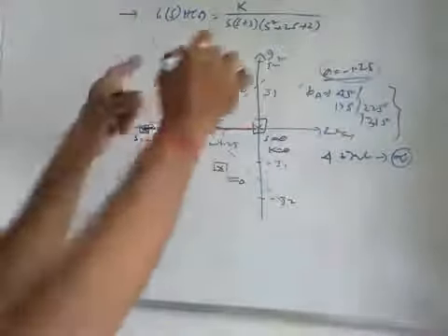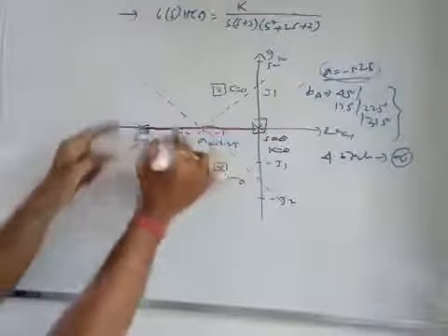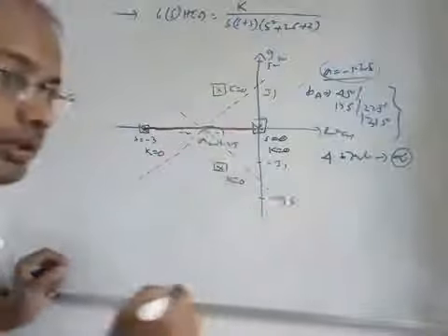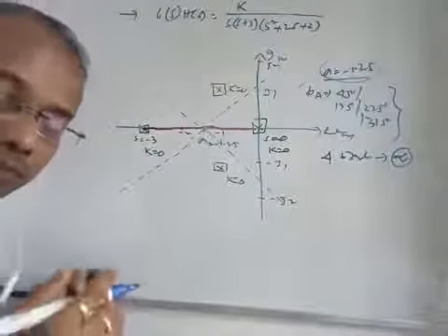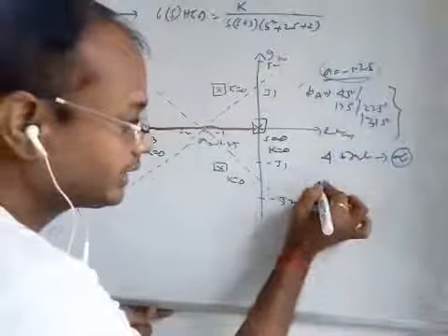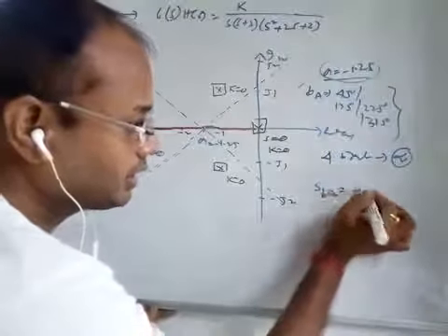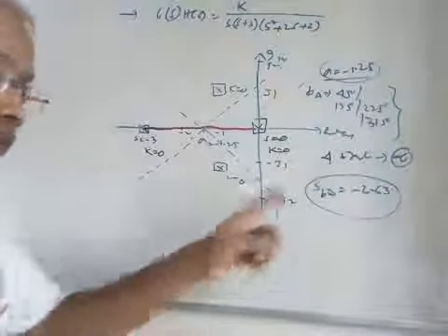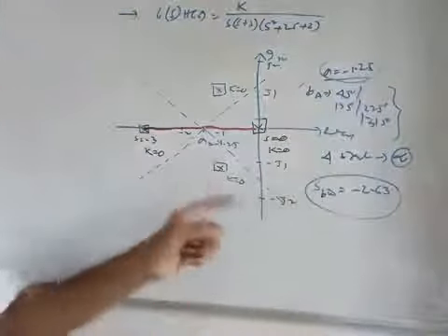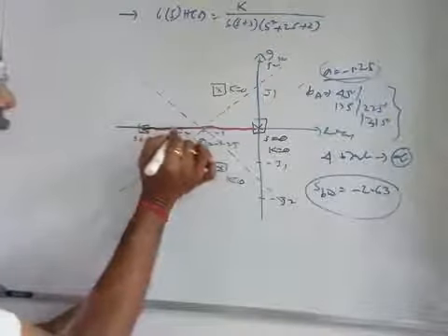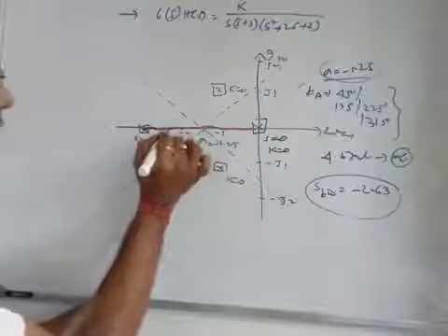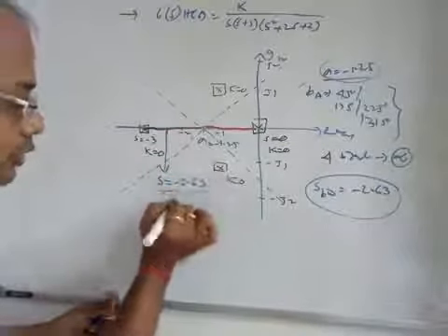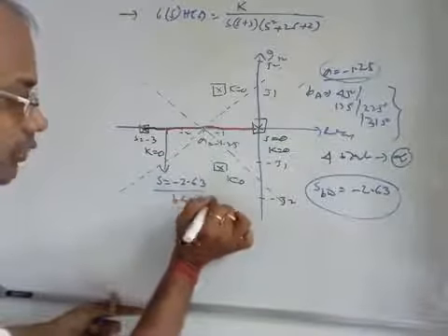Now we have calculated the breakaway point, because there is a breakaway between 0 and minus 3, and during the breakaway point determination there was a problem, and we have worked on the problem, and finally we get breakaway point is equal to minus 2.63. This is the approximate solution, and that value is near about this point, say 2.63, that is here. So this is your S is equal to minus 2.63, which will be known as the breakaway point, right?